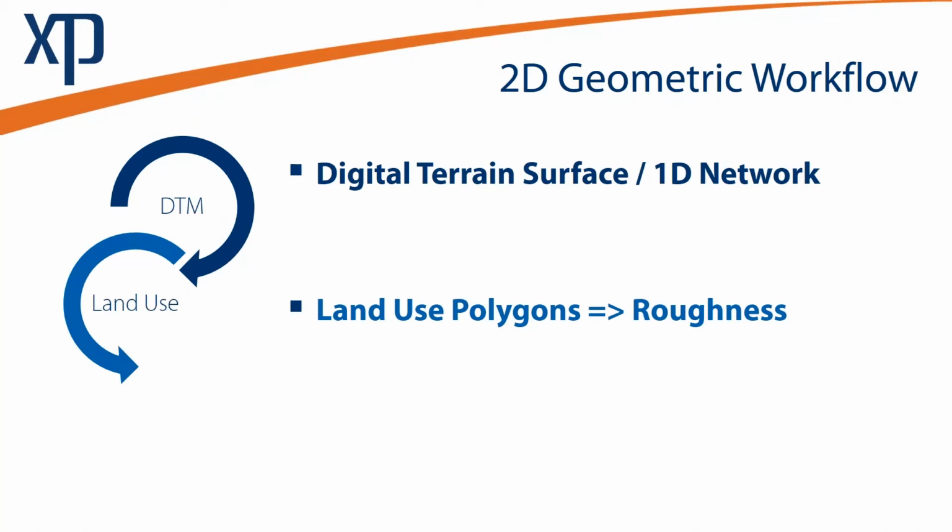We're also going to utilize land use polygons or the absence of polygons to represent roughness. And we'll use the default settings for our 2D model to represent a roughness for the entire model, except for those elements that we've specifically defined, so that you don't have to make a grass element and make a polygon that contains everything but the roads.